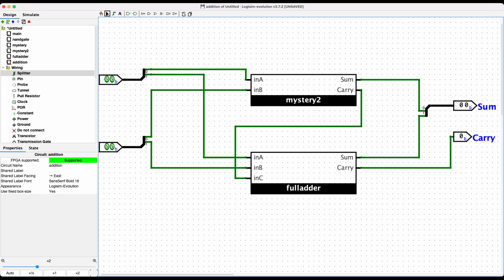Okay, and similarly, what do add C and add CS do? In addition to just adding, they also take into account the result of the carry flag. So the ARM addition unit is actually going to be all full adders, because the carry flag, if we were to use it, would need to come in. Okay, does that make sense? None of them are half adders, because we have a carry flag that we might want to use.